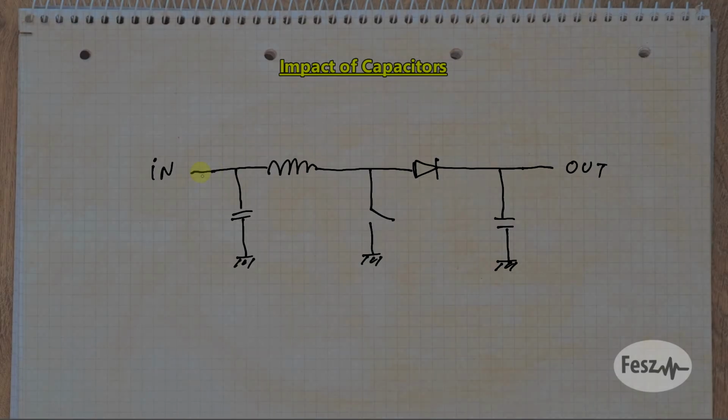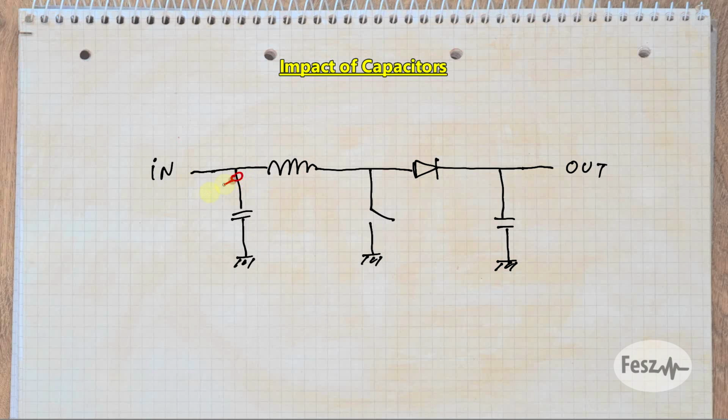To finish our initial noise analysis, the last thing that I want to look at today is the input and the output capacitors. As we've already seen, both the input and the output do contain quite a bit of noise, so let's see why that actually is. Based on the current analysis, we know our capacitors are experiencing variable current, so the voltage at their terminals will also be variable. For the boost, the input sees a triangular current, and the output a trapezoid current. So let's see how the voltage on a capacitor looks when exposed to such a waveform.